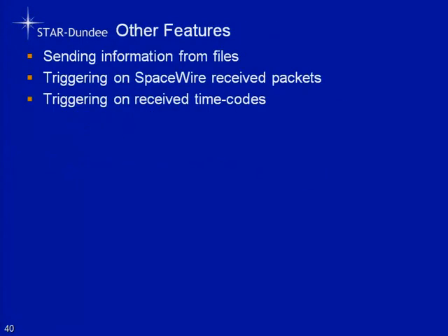Okay, so just to follow that example through, you've got your camera emulation. It receives a command to say switch it on. That command goes in, it gets matched, that matching causes a trigger, that trigger causes you to change state, and in the next state you're then starting to send out images repeatedly every 100 milliseconds or whatever it may be.